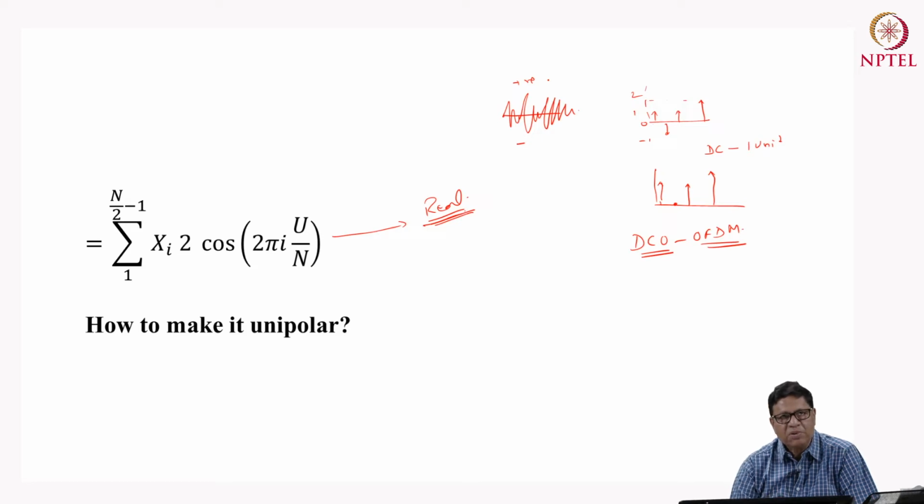You have to give more power to the signal. And if I shift too high, I basically shift even the most negative signal to a positive value, but then it results in a power inefficient system. And if I don't do that, then there may be some clipping.